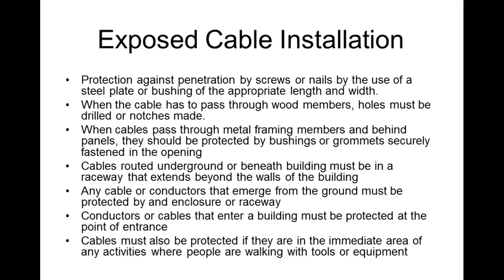When cables pass through wood members, holes must be drilled or notches made. When cables pass through metal framing members or behind panels, they should be protected with bushings and grommets securely fastened to the opening.